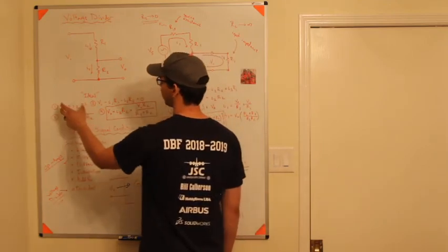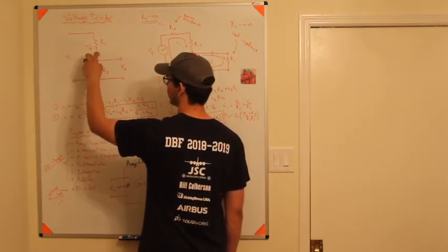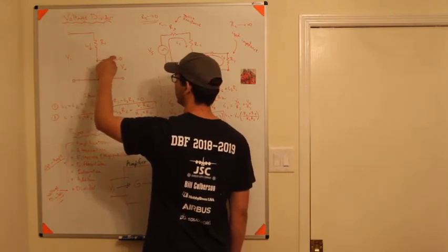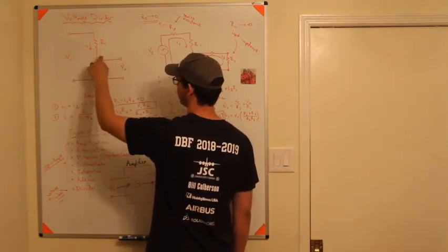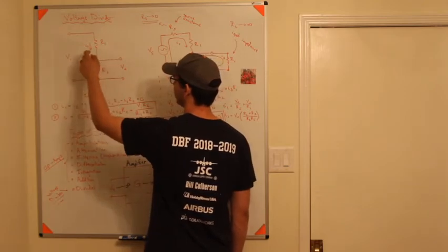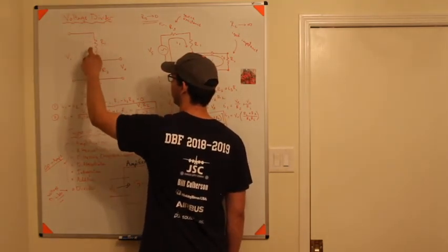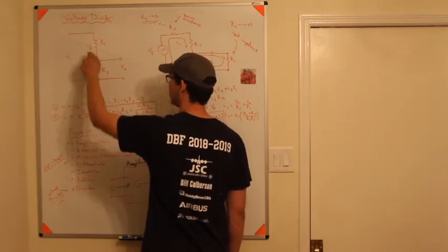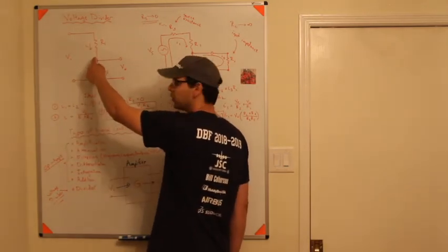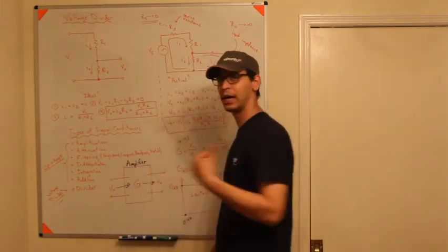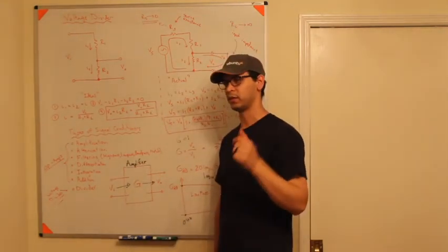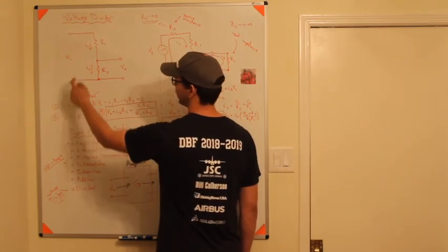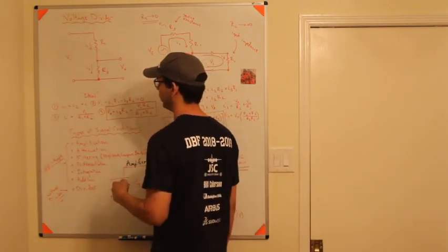You can also do a nodal analysis where you look at this node and say, I'm assuming that there's nothing hooked up here, so there's no current going this way. And so I1 is equal to I2, because the amount of current going into a node is the same as the amount of current going out of a node. And I think that's called Kirchhoff's current law. So I1 and I2 are really just I. There's just one current running through this whole loop here.